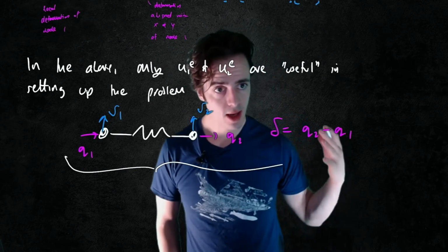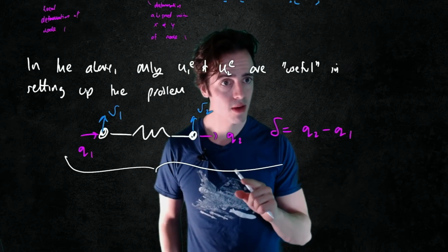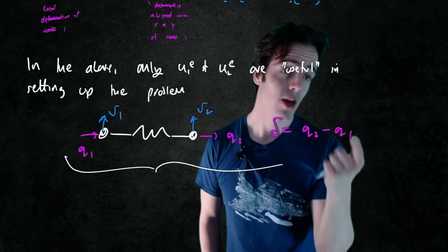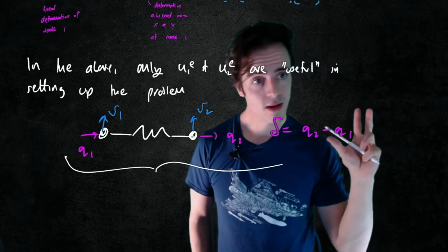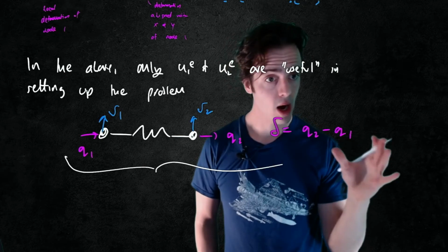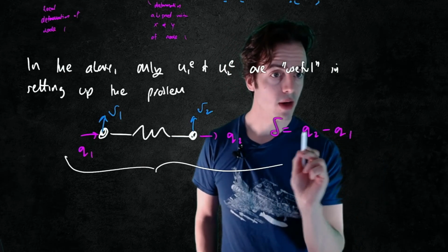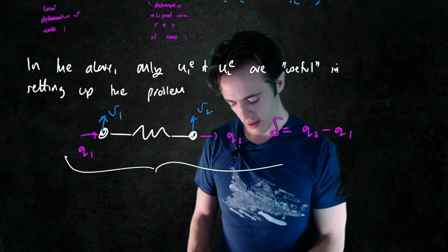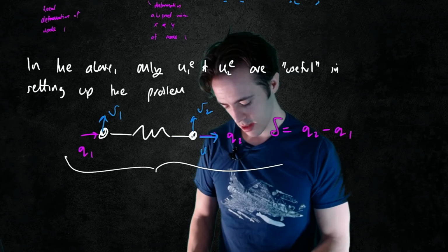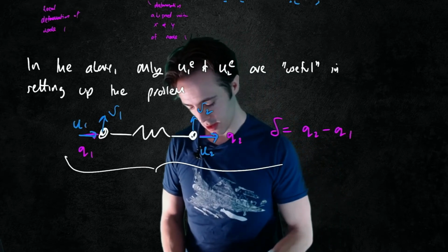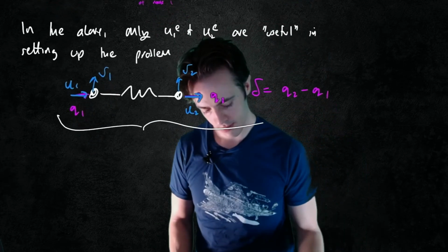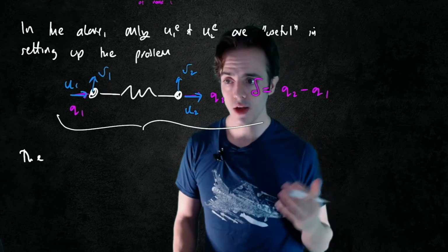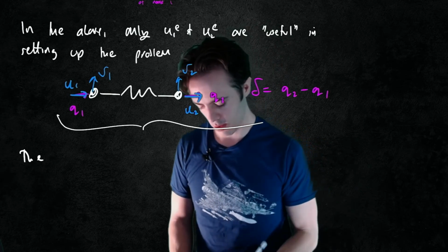So for uni-axial two force members, i.e. a spring, or for a truss bar, a truss element, all we care about is those displacements here. We called them Q when we were looking at springs. These would actually be U2 and U1 for this case. So the total elongation of the elements is just going to be, for us now, U2 minus U1.